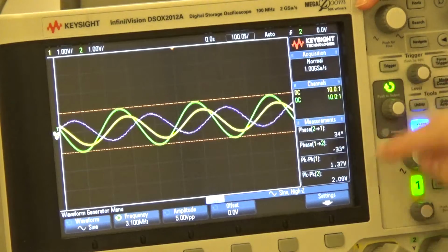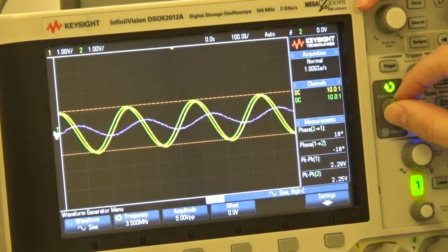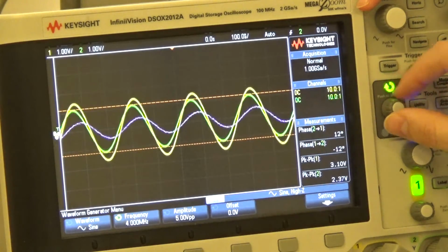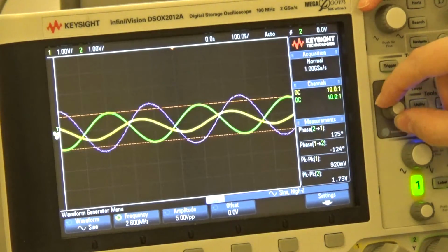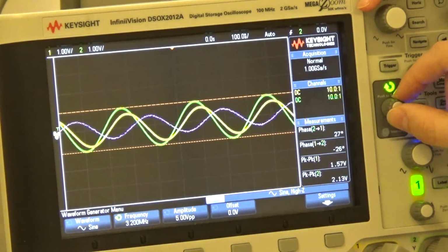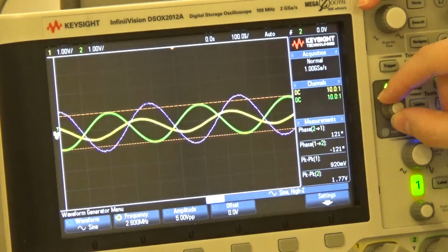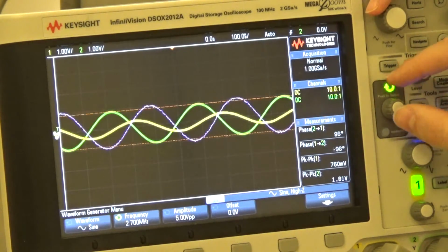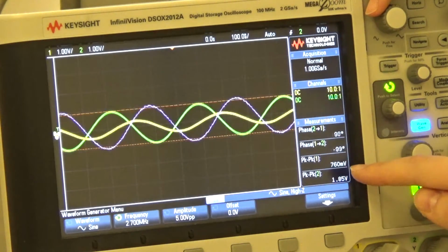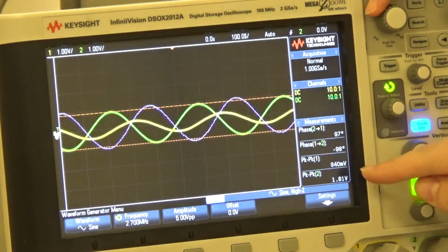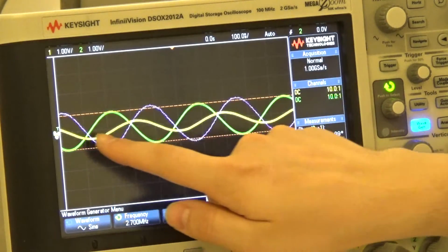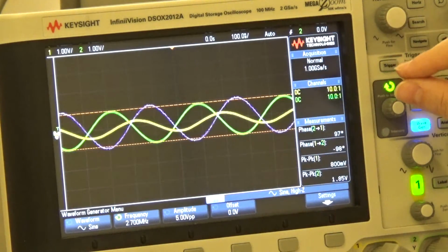Okay, so again the channel 2, which is the inductor's voltage, is beginning to decrease, I think. And at these points should be our resonance. Just find where the yellow waveform is the smallest. I think it is smallest at 2.7 megahertz. It is coming as 700 or 800 millivolts.